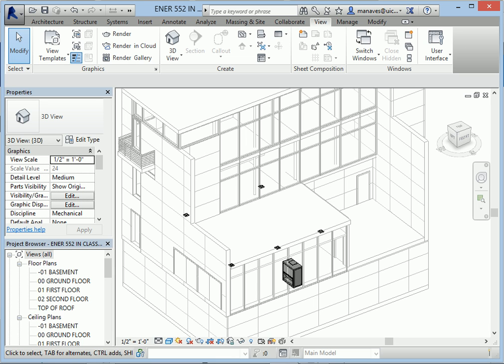Okay, so by default, I was working in architecture template. The architecture template doesn't load all the mechanical, you know, tees, elbows, and so on. So when we try to make a system, it just won't make it because it's missing everything, and it won't tell you it's missing everything. So Revit has this on purpose so that we can then import.